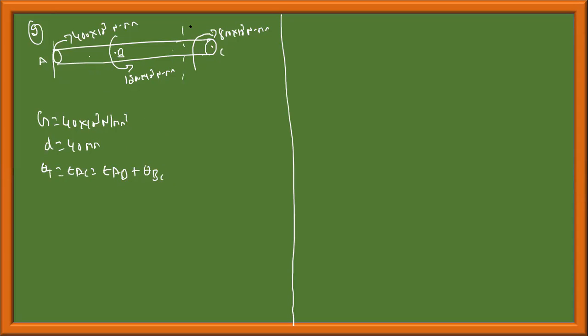I will take the section here, XX. Anywhere you can take between B and C. This is section C. Here 800 into 10 power 3. If this is the length direction, and you bend your fingers along the length direction, if your thumb points away from the section, then your torque is positive. Or you can assume that along the length direction, counterclockwise torques are positive. But this torque is clockwise, and I will always apply a torque acting away from the section. That is TBC.